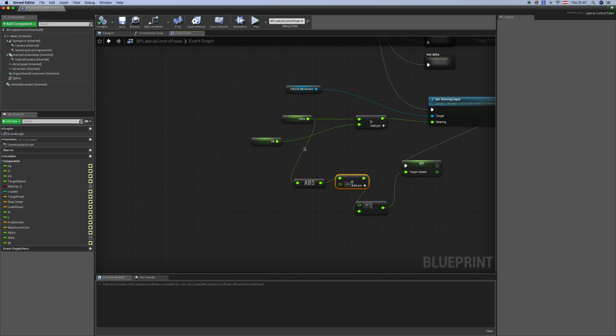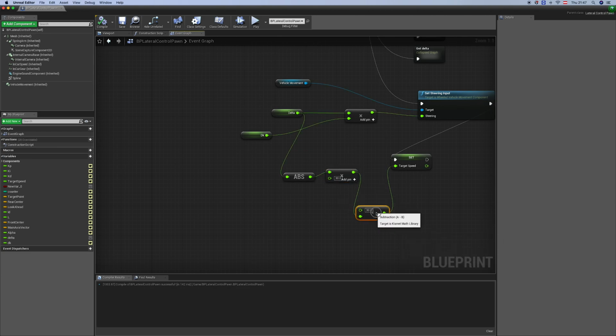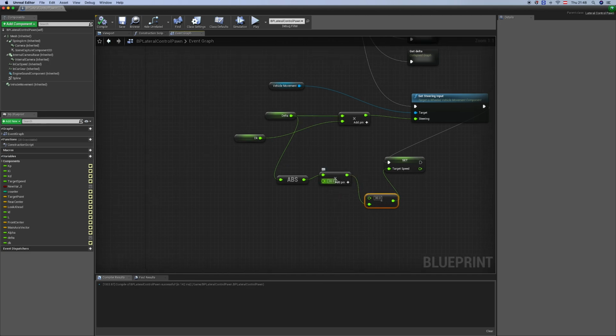So what I've done here is taking the delta value that we have already calculated. This is basically the reference or the highest speed, which we set to the target speed that the PID is following. So we have the 30 here, which is our maximum speed, 30 kilometers per hour. And we are subtracting a value, which is a function of the absolute of delta, because we don't care about the sign here, we care about the angle itself. So we are multiplying delta with a factor 30. The 30 is not required to be equal to the maximum speed. It's just experimentally I found that this factor is enough for the speed control. So if we do so, we get speed control plus steering control together, as we'll see.